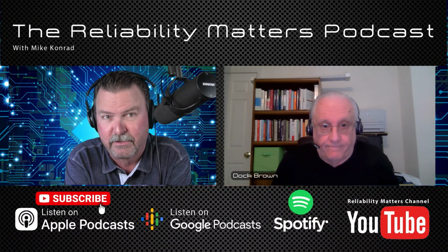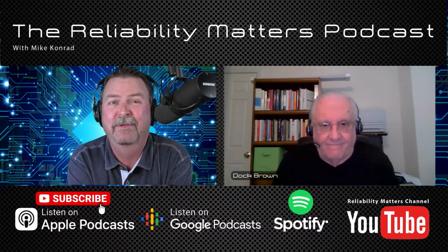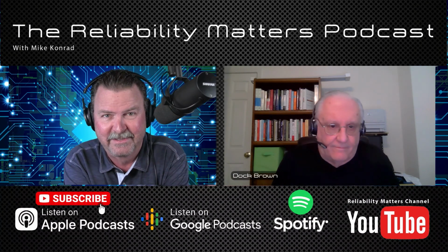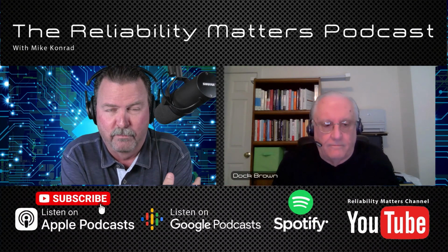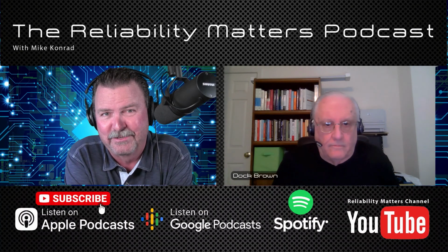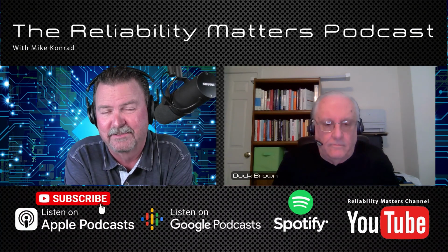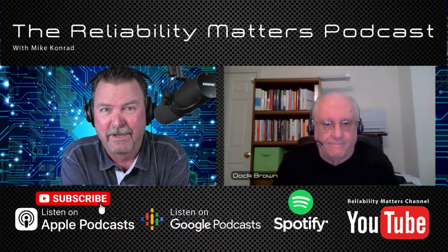I'm glad you said rinsing and drying. Drying, most people forget about. But as you well know, in your Ansys world and reliability world, that CAF is a big issue. Conductive anodic filament is a measurable issue in our industry, and you can't clean your way out of a CAF problem, but you can certainly dry your way, at least for a while, out of a CAF problem.